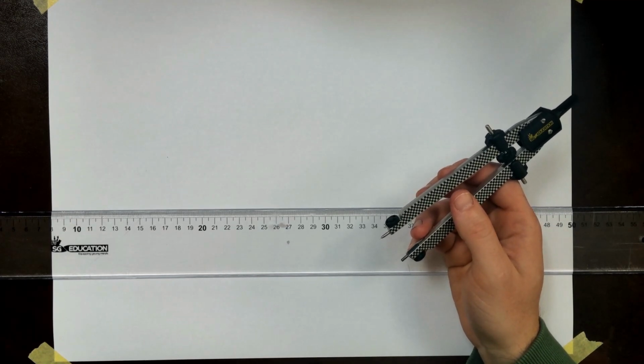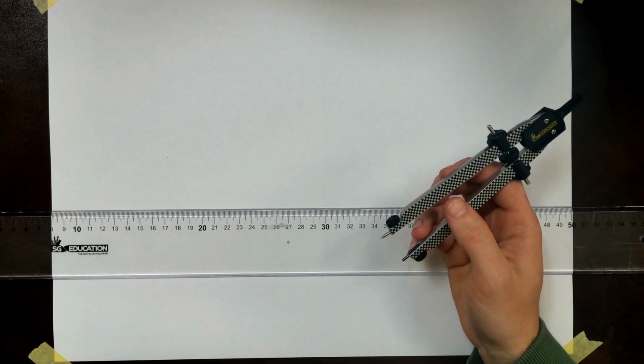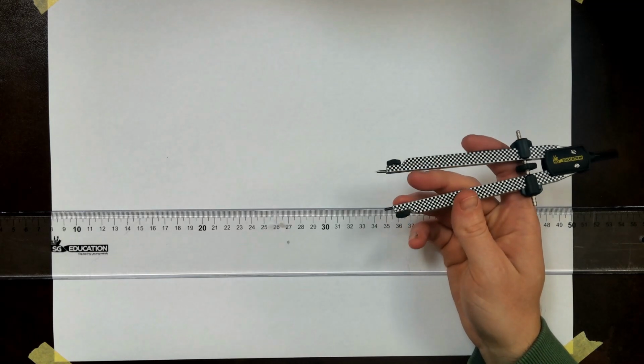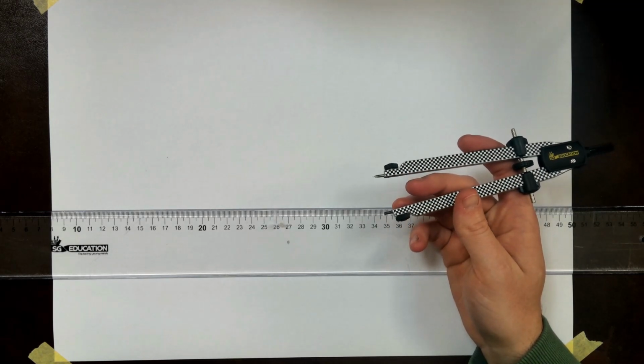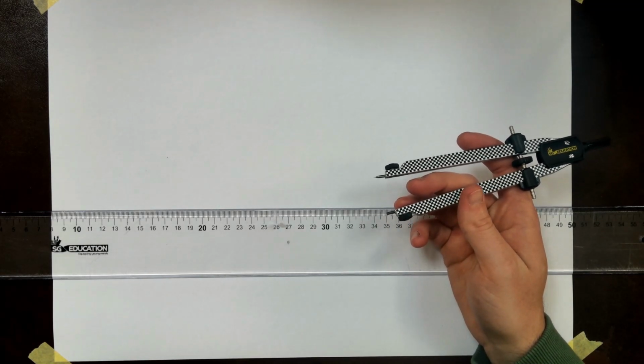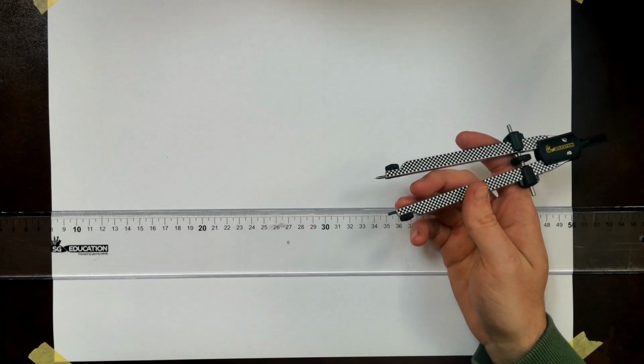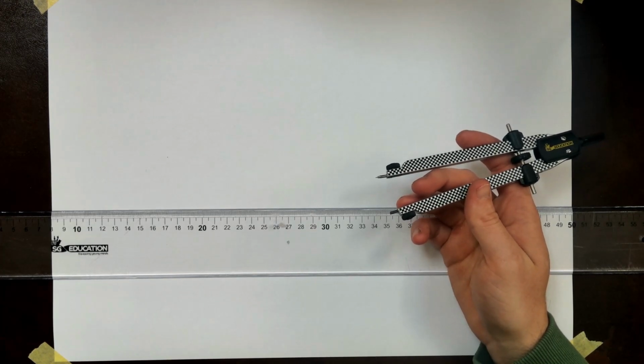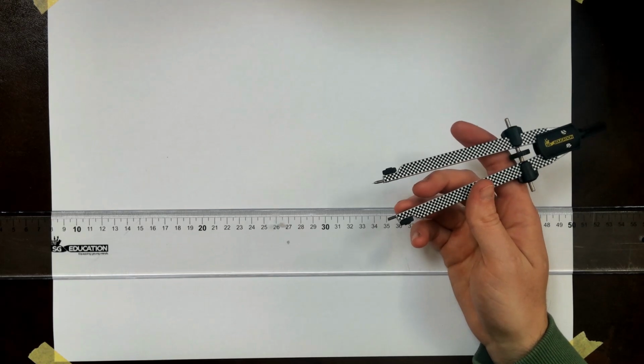So they're giving us the measurements for the actual CAM, and they've instructed us that the curve going from A to B is an involute of the circle, the radius 18 circle that's on the inside. And then they want us to draw the displacement diagram that corresponds with this particular CAM. So we have to draw the CAM first.